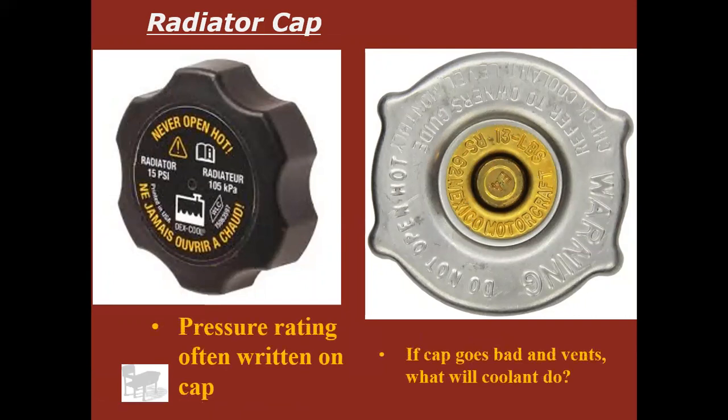If the cap goes bad and vents, the coolant will boil. Okay, you do not want coolant to boil. If coolant boils, a pump can't pump it. Water pump's made to pump liquid, not air. So if you get boiling coolant, it will not cool the engine, it will overheat. That is an ASE test question.